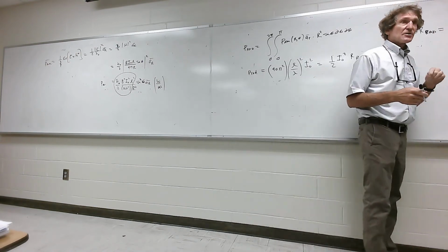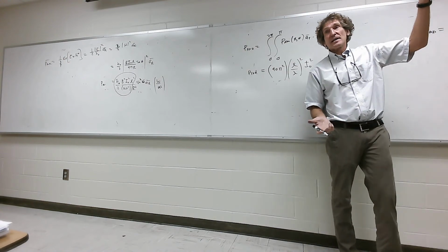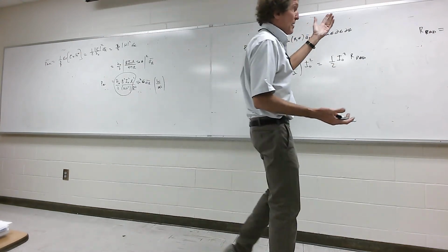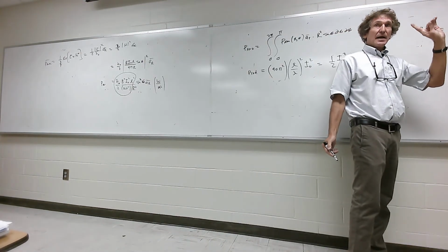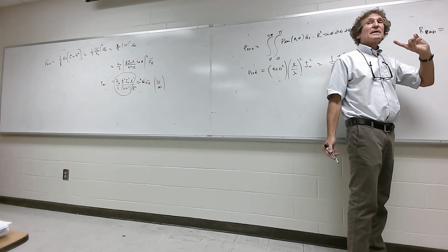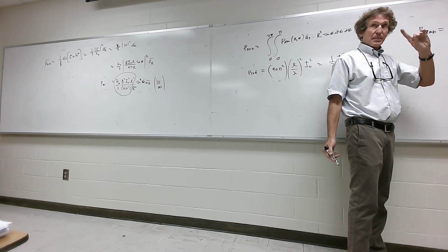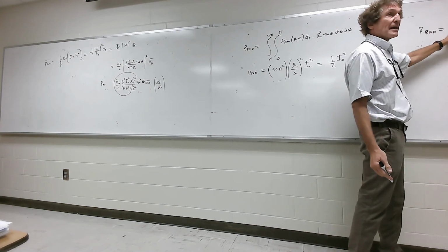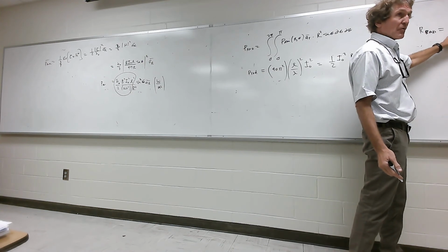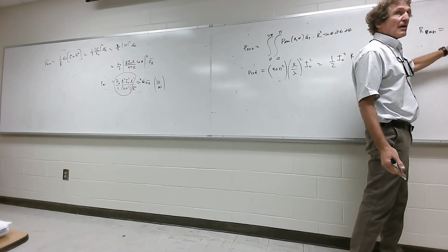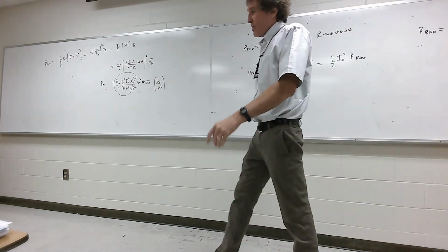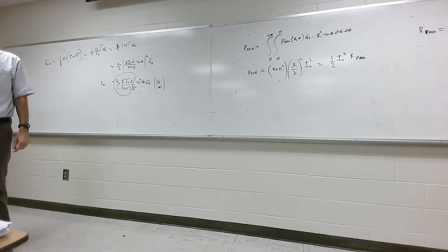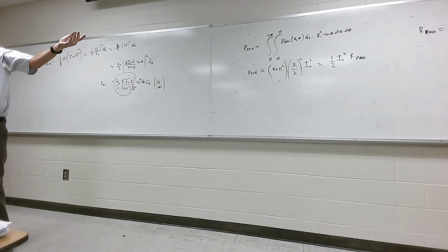Now, to give you an idea how small this is. We'd like it large, so we could have a small current generating a lot of power. We'd like that. But remember, I said L over lambda. L has to be only 1/10 of a wavelength or less. That makes this 1/10 squared, 1 over 100 times 80. That's 8/10 or 4/5 pi squared. Call pi 3, squared that's 9. 4/5 times 9, this is of the order of tens of ohms, and less. Got me on this?